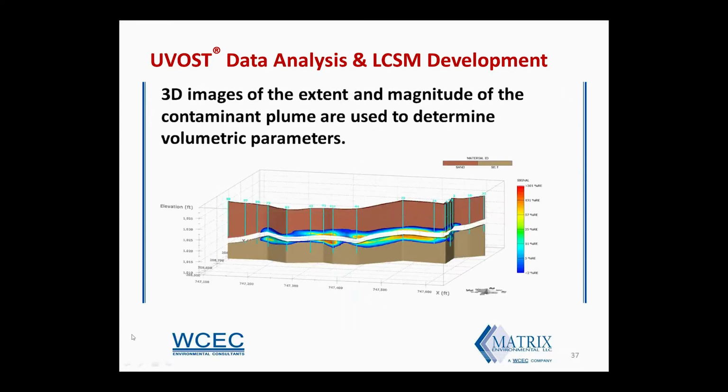Another static deliverable from the same project, this is actually a fence diagram that's similar to the one of the cross sections you just saw. This one is interesting. We did a high resolution characterization of the subsurface coupled with a super accurate survey of the ground surface at the site to give us a depth of each NAPL interval and an accurate depth of this geologic interface that you can see along where the sand and silt layers are exploded.